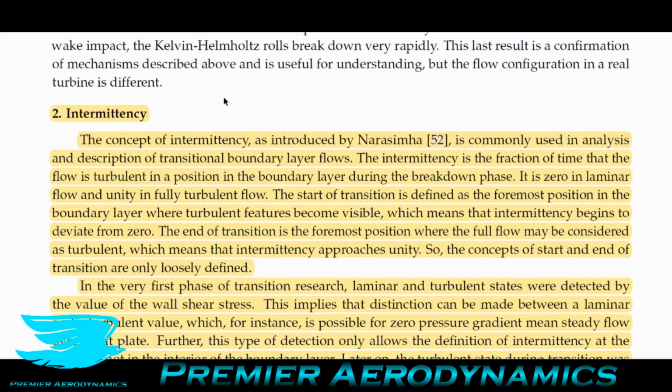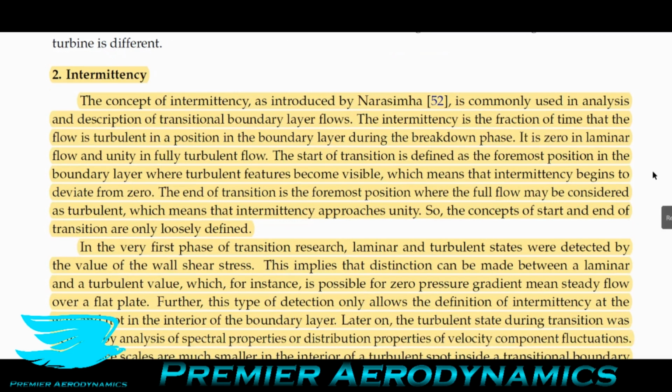The concept of intermittency was introduced by Narasimha. It's commonly used in analysis and descriptions of transitional boundary layer flows. The intermittency is the fraction of time that the flow is turbulent at a position in the boundary layer during the breakdown phase. So in other words, it is 0 in a laminar flow and 1 in fully turbulent flows.